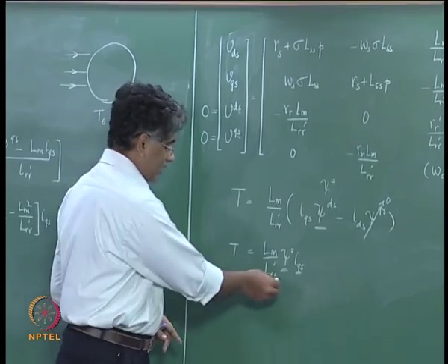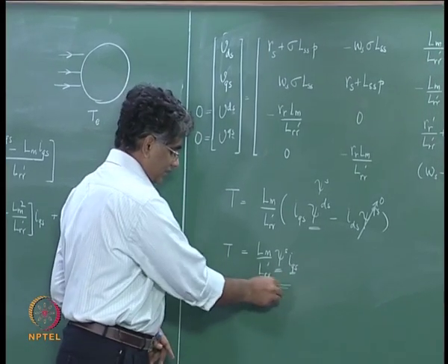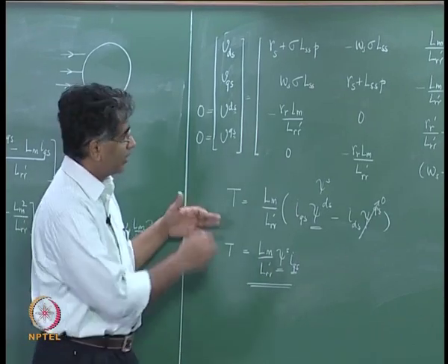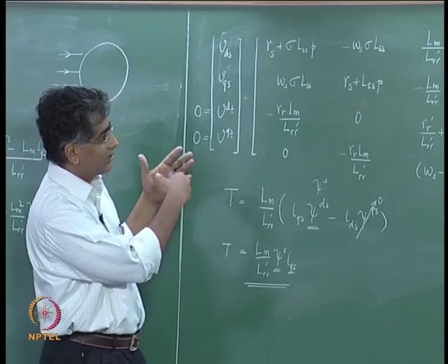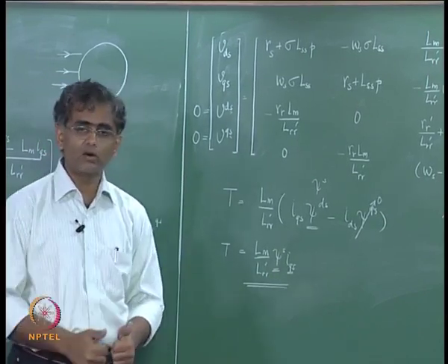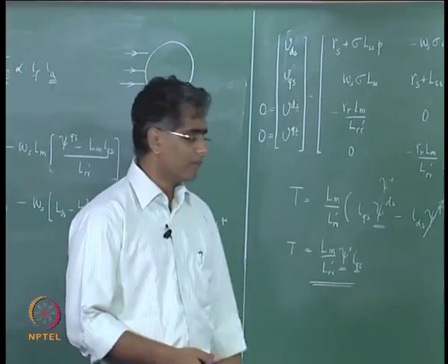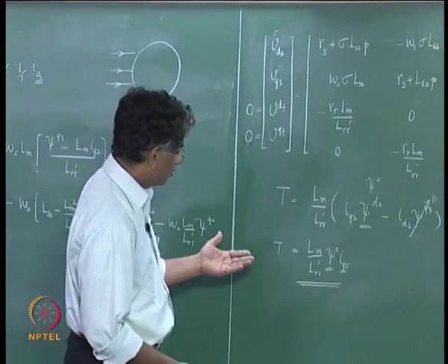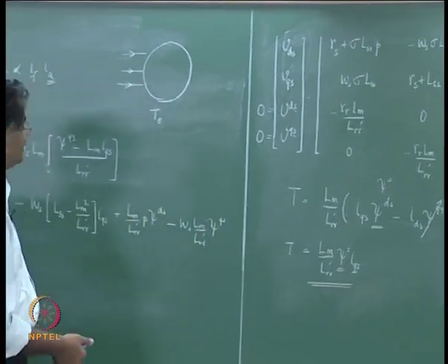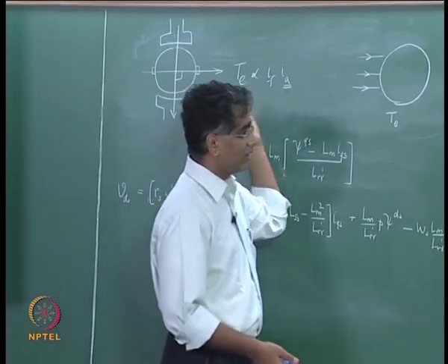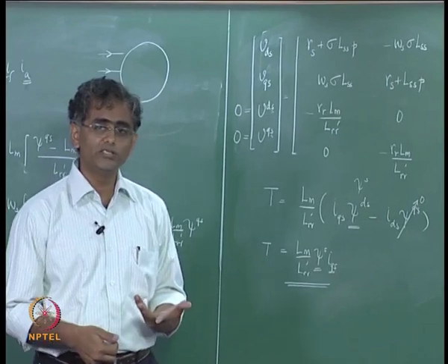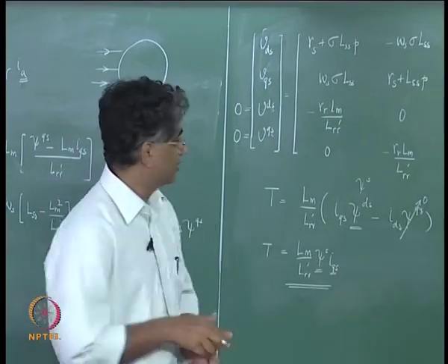This expression means that by transforming to the synchronous reference frame with the d axis aligned along the rotor flux vector, we are looking at an induction machine which behaves essentially like a DC machine, and therefore in this reference frame the machine should be much easier to do closed loop control.